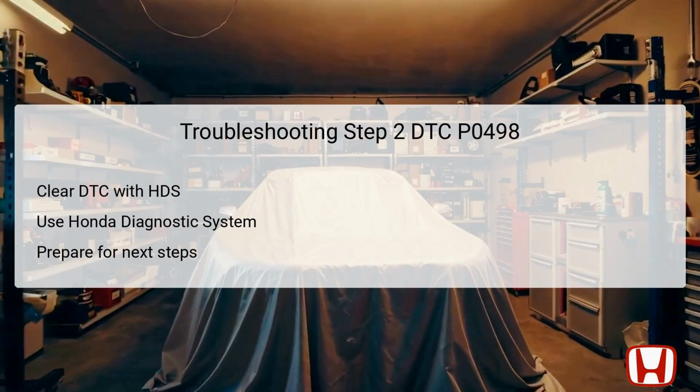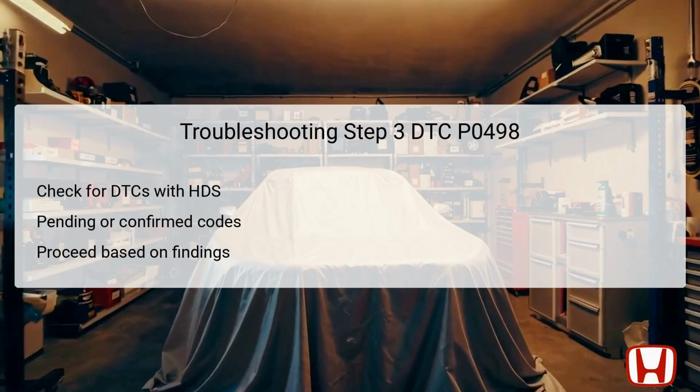It is essential to follow this step carefully as it prepares the vehicle for the next stage of diagnostics. Using the HDS ensures that any stored codes are entirely removed, allowing for accurate testing to commence in subsequent steps, enhancing overall diagnostic accuracy. In this step, the technician should use the HDS to check for any pending or confirmed